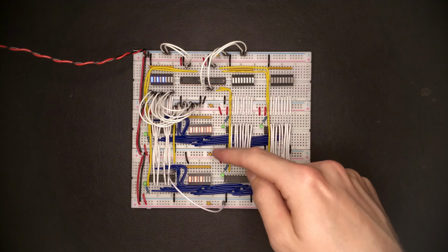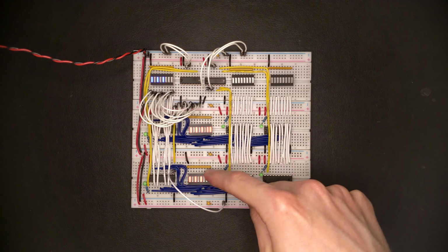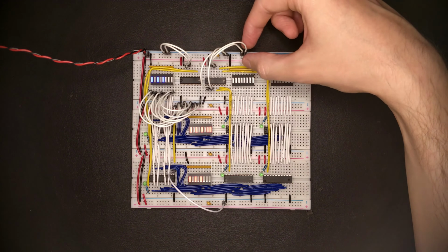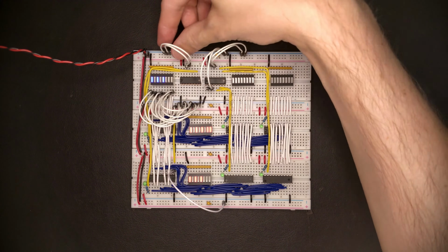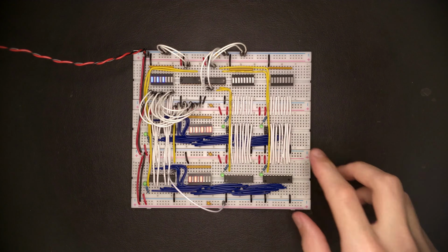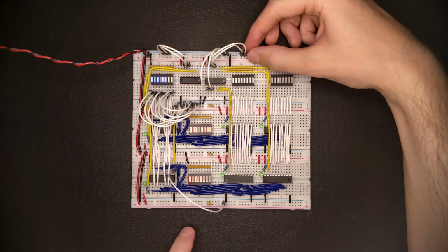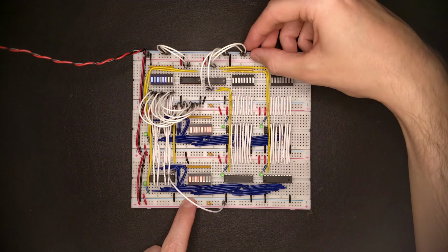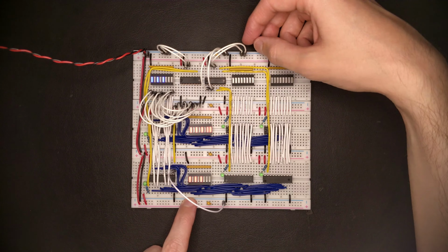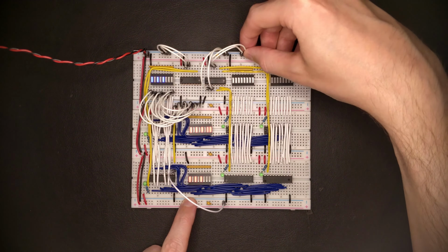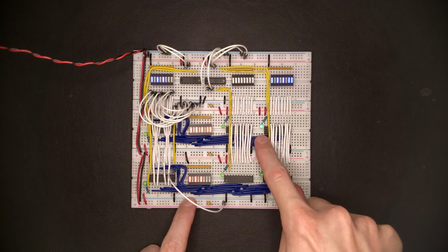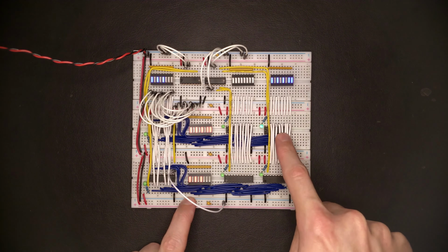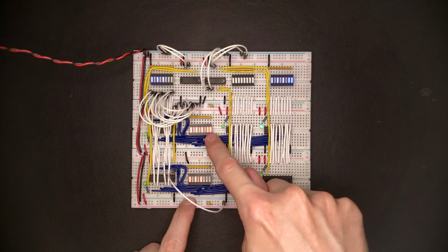All right, so this brings us up in some random state, which happens to reflect what was stored in the registers before. And now we should be able to use these 2-bit register addresses here to select which of the registers should do something. So this here is read address 2, which corresponds to the read data bus 2. Currently this is at 0, but if I increase this to 1, you can see that we actually select register 1 for outputting on this read data bus, and we can see the value of register 1 appear here.